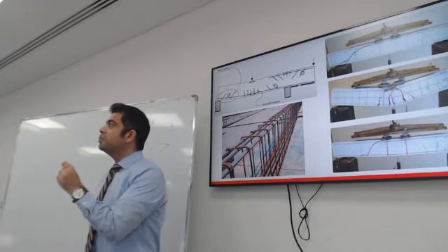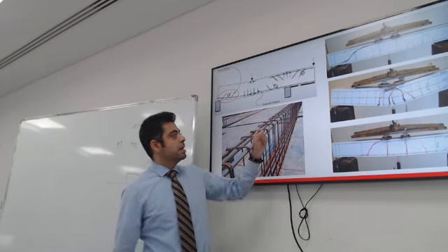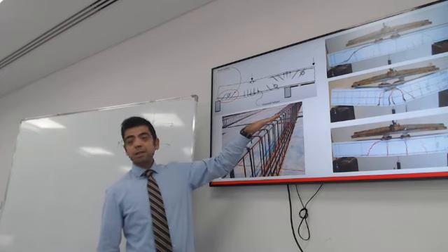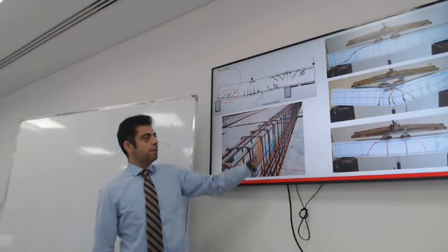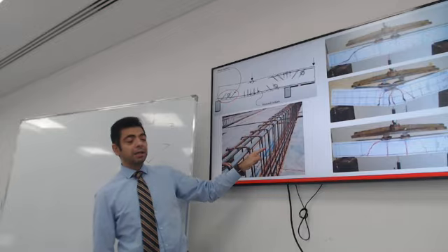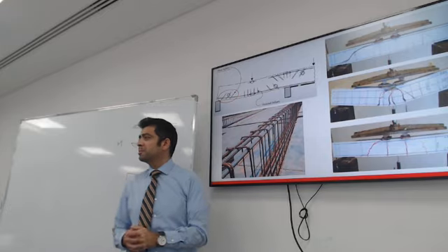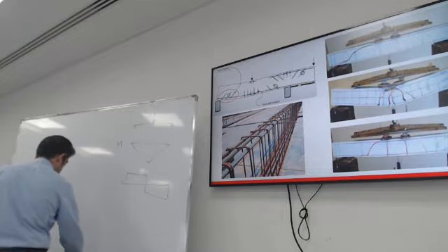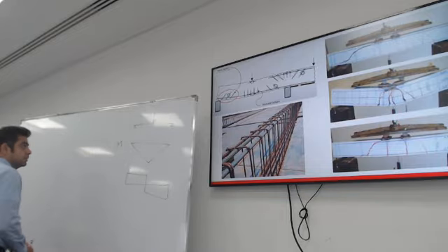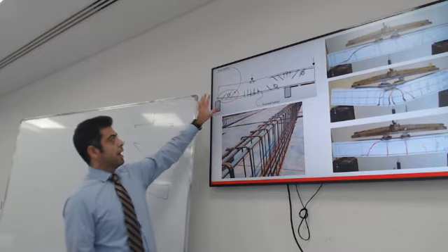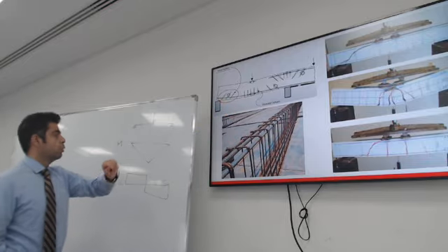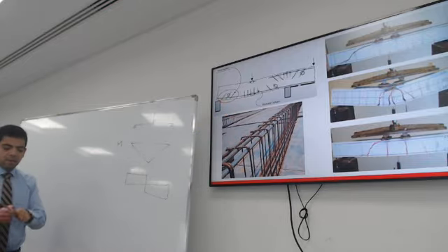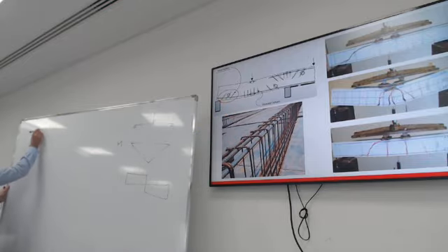Yes, you need reinforcement not in the longitudinal direction, you need it in the perpendicular direction. You need those links, shear links or stirrups. And let me show you very quickly how that works. I will take the far end of the beam where maximum shear is and try to study what is going on.